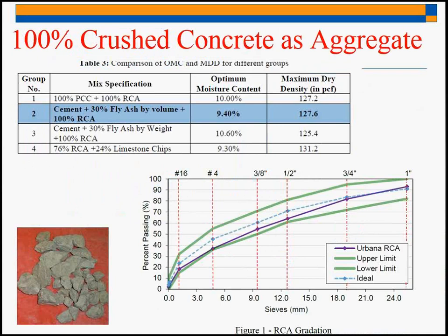The next is the study on the crushed concrete in the RCC, and this has some interesting properties because crushed concrete has a high absorption capacity, so it's very hard to get an exact optimum moisture content for it and to create a good actual mix for the design.